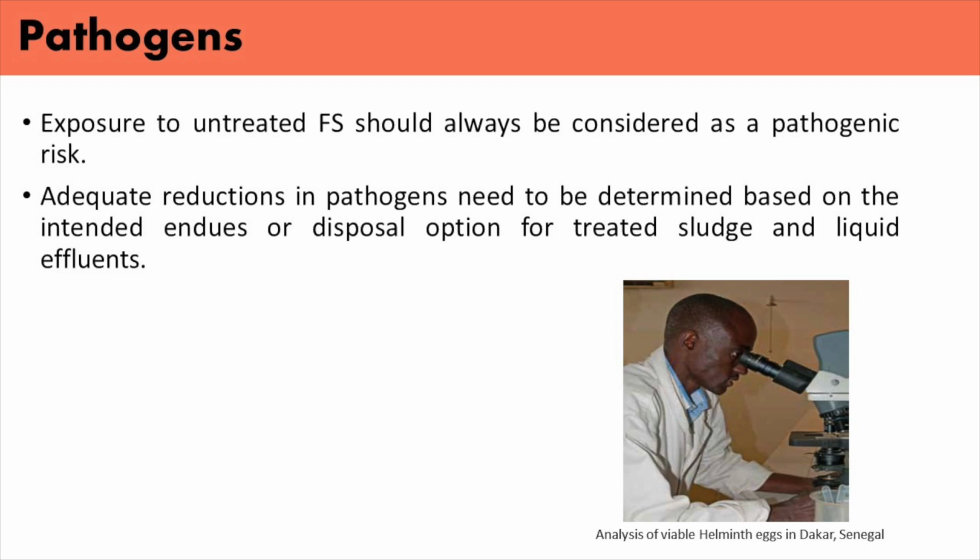Exposure to untreated fecal sludge should always be considered a pathogenic risk. Adequate reduction in pathogens needs to be determined based on the intended use or disposal option for treated sludge and liquid effluents. Some common pathogens of concern that may be excreted in feces are presented here.